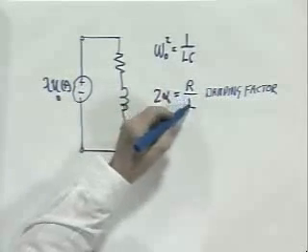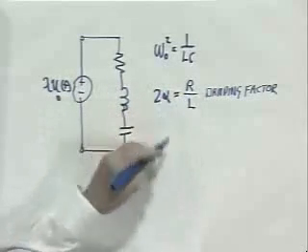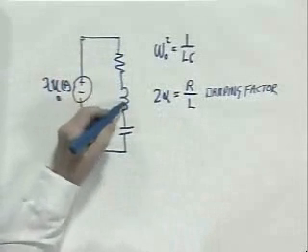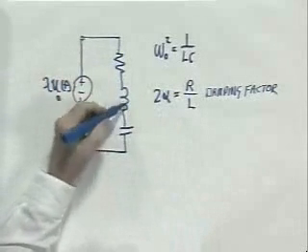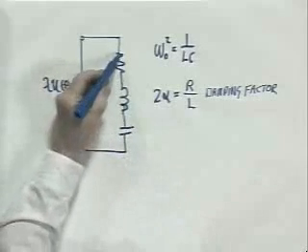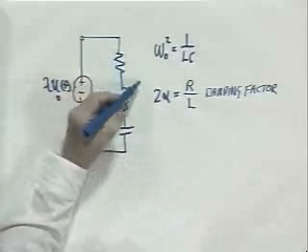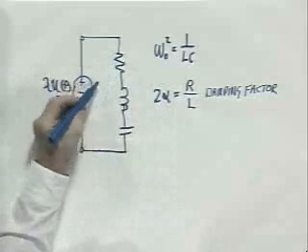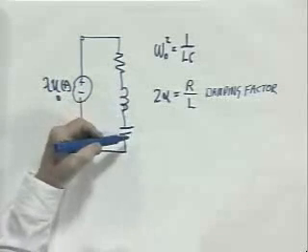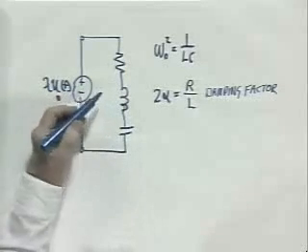If I make R very small, that's making alpha very small, it's making the circuit lightly damped. As R goes to 0, this is just a series LC, which will go on oscillating indefinitely. But the loss mechanism, which is a series resistance in this case, steals a little of that energy being swapped back and forth between the L and the C on each cycle, and eventually decays to 0.